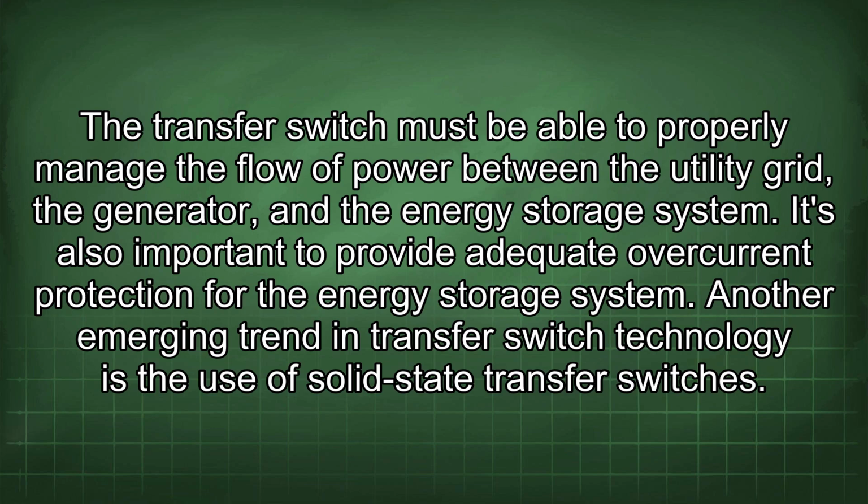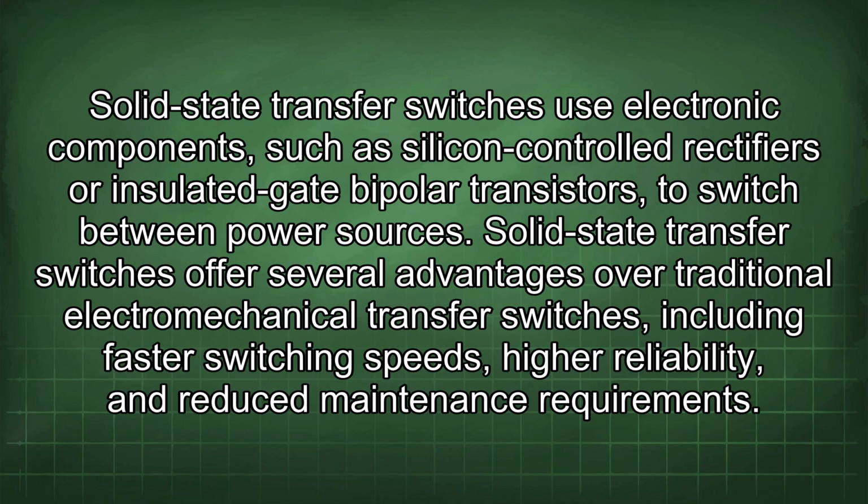Another emerging trend in transfer switch technology is the use of solid-state transfer switches. Solid-state transfer switches use electronic components, such as silicon-controlled rectifiers or insulated gate bipolar transistors, to switch between power sources. They offer several advantages over traditional electromechanical transfer switches, including faster switching speeds, higher reliability, and reduced maintenance requirements.